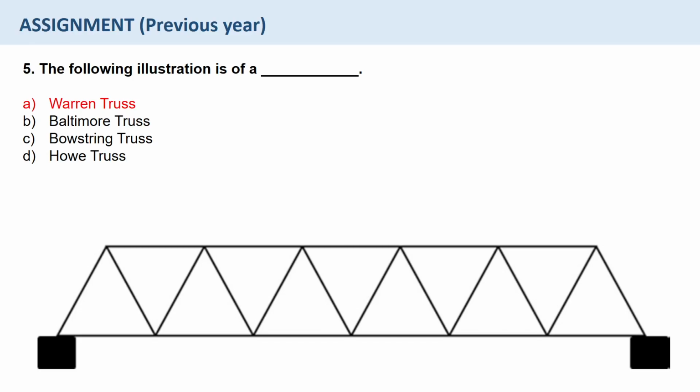Pneumatic structure, as explained in previous questions, is a membrane structure which is stabilized by pressure of compressed air. Pneumatic structures are characterized by slightly higher pressure of internal air above the outside pressure. These structures are supported by pressurized air within the inflated building elements that are shaped to carry the loads in a traditional manner. Folded plate structures are assemblies of flat plates or slabs inclined in different directions and joined along longitudinal edges. In this way, the structure system is capable of carrying loads without the need for additional supporting beams along the mutual edges.